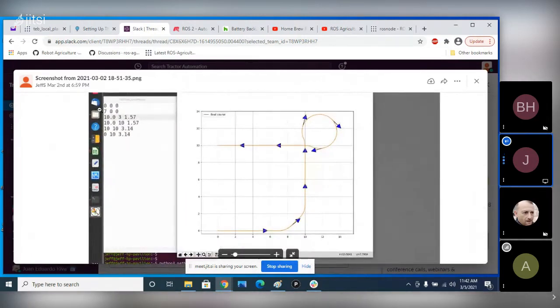So in this case, it says start at 0, 0, which is this point right here on this graph, and we say go to 7, 0, which is this point right here. And then I'm using that same technique we just had. No, this is actually the other method where I'm defining a horizontal line and I'm defining a vertical line. And the point is you have to say go to some point that's where you want your corner to be, but you can't go all the way to the corner. So you back off one radius from where you want to go.